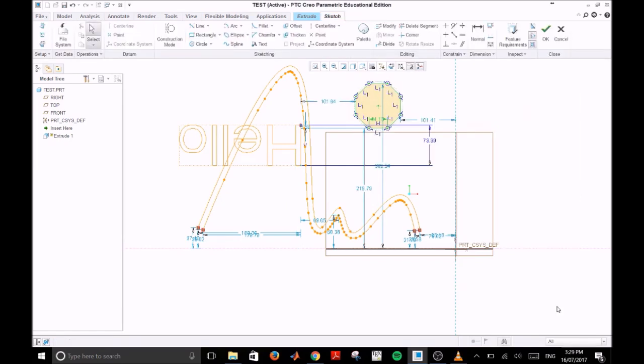So as you can see, there are many ways to make certain shapes in sketch mode. A good process for the workflow is starting with simple shapes like rectangles, circles, arcs, and lines, adding those together, and then modifying those with the Delete Segment tool to arrive at your required geometry. At this point, I suggest the user to basically have a play, to enter sketch mode, and to experiment with each of those tools to see what they can achieve.